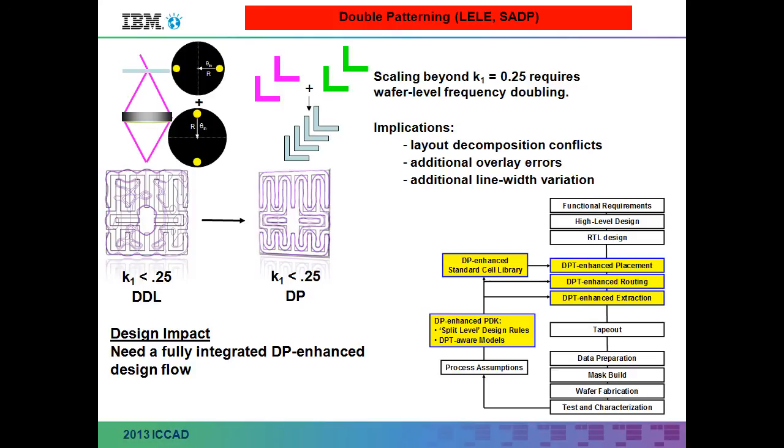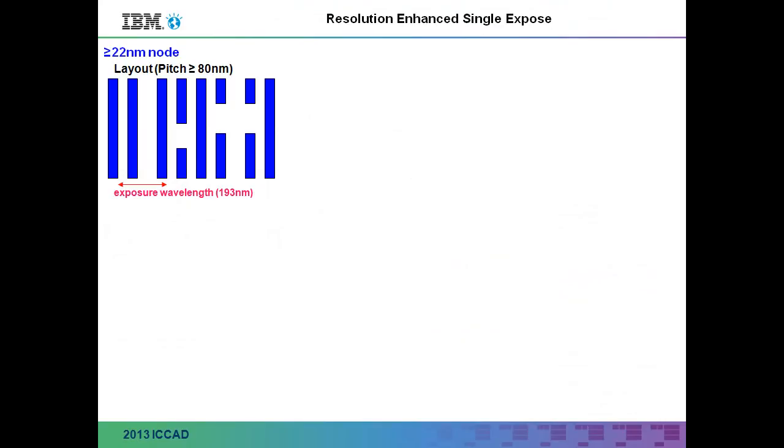And that, of course, is one of the double patterning techniques. We call it litho etch, for kind of obvious reasons, after I just explained to you how we do this. And that takes us beyond this resolution limit of K1 of 0.25.